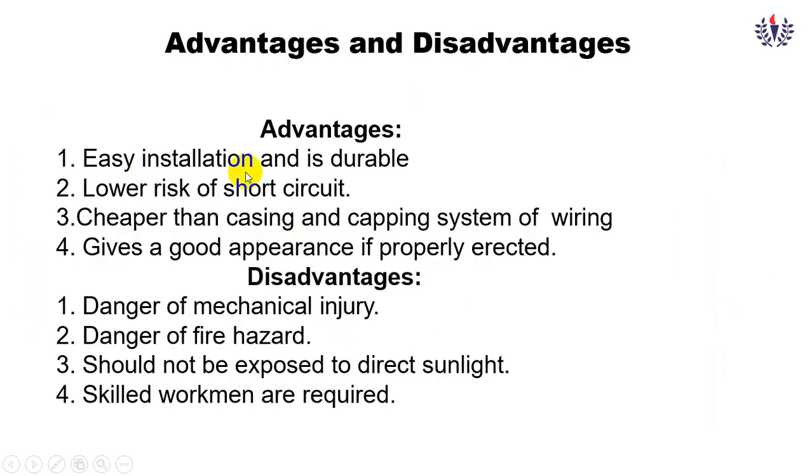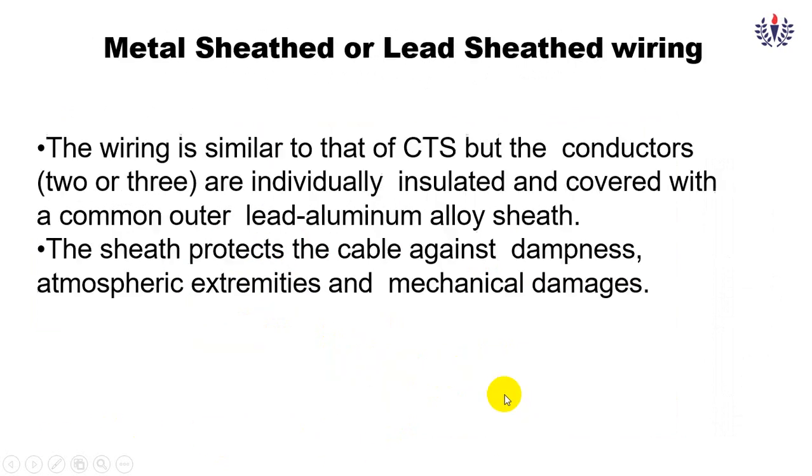Here also installation is easy and durable, low risk of short circuit, cheaper, quite cheap, no chasing and capping, and gives good appearance if it is properly erected. So this is somewhat okay. So not looking odd, but there is danger of mechanical injury, and fire hazard is there. It is exposed to direct sunlight, and also skilled workmanship is required. So making it pinned, it requires skilled workmanship.